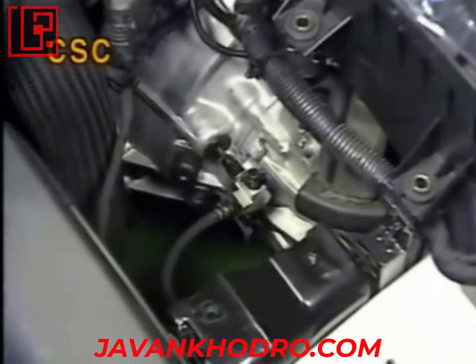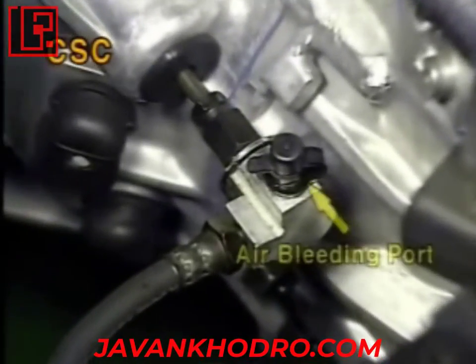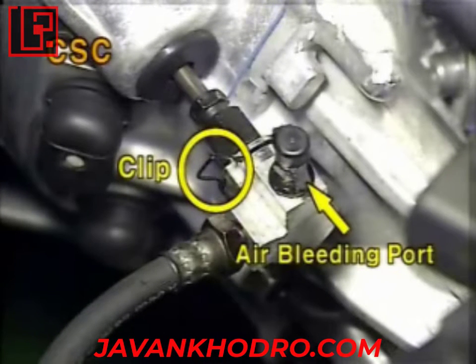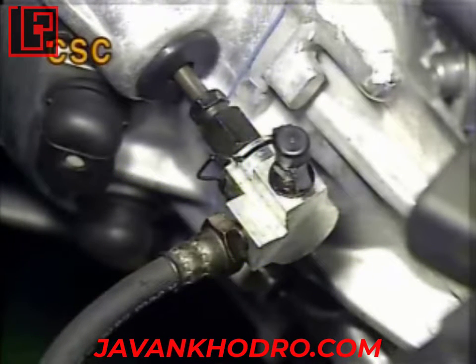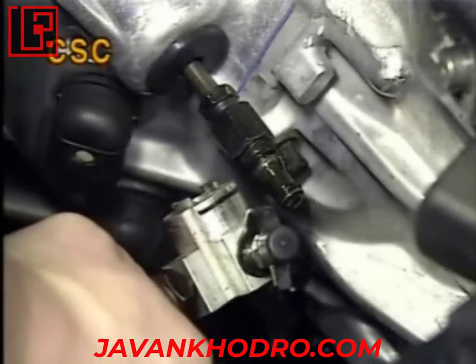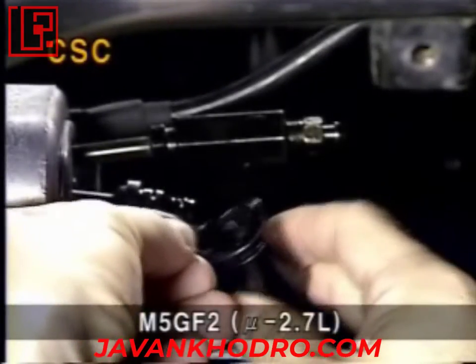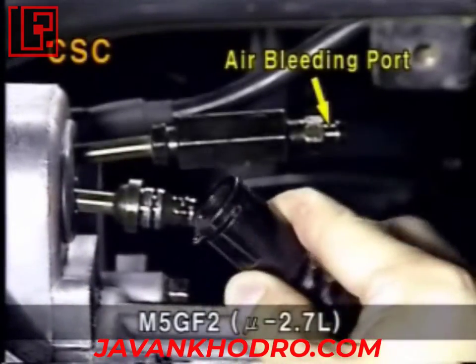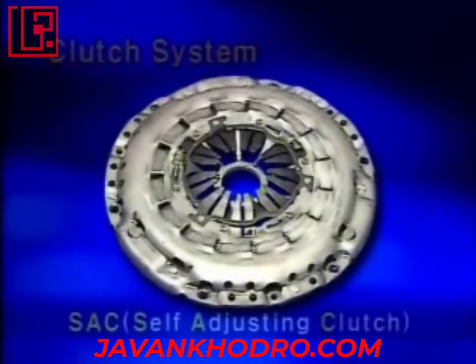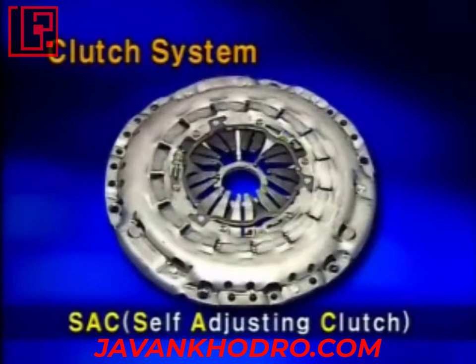CSC comprises the hydraulic hose connector and the air bleeding part. For removal of the CSC and the hydraulic hose, remove the clip, pull the quick connector of the hydraulic hose to take it off. Exceptionally, for the M5GF2, an additional air bleeding pipe is installed. The clutch system is applied with the new SAC, self-adjusting clutch.